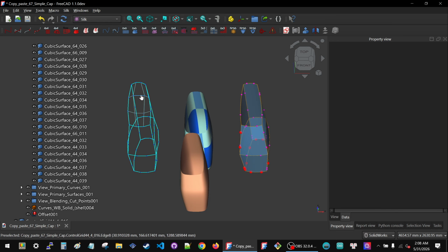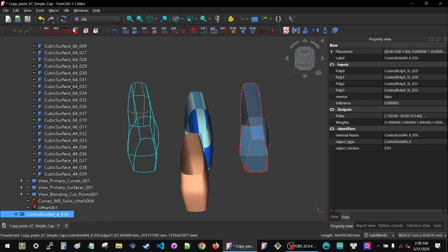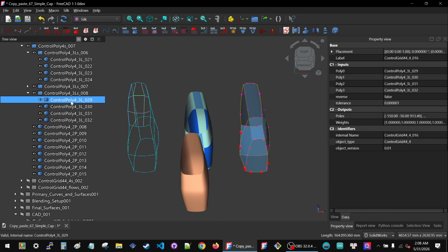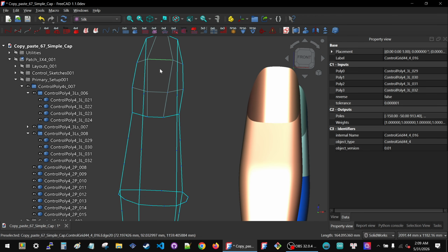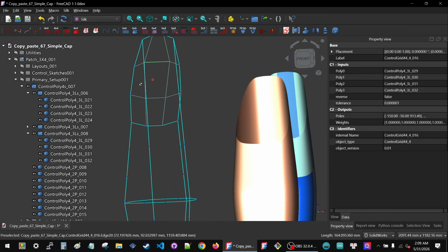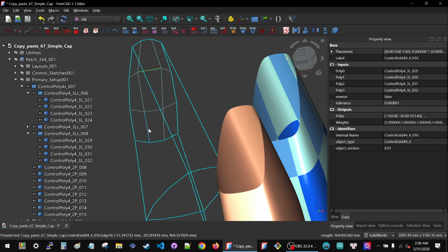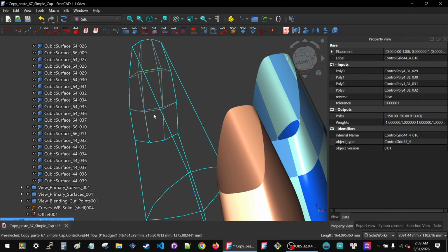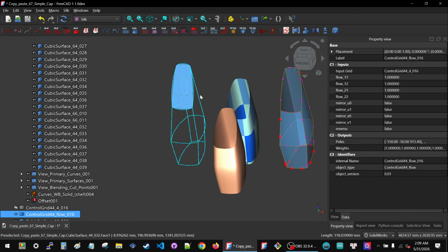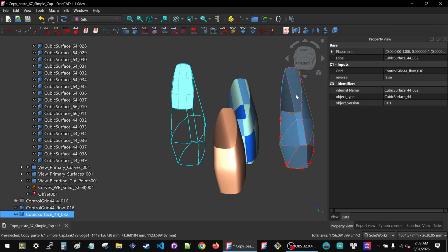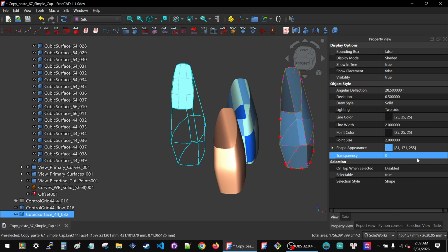Okay. I have this object, I have this grid here. I could give it a flow grid. You know what? I'll do that. I'll give it a flow grid because I did it on all the other faces. So right now this is the default grid, which has parallelograms in all the corners. I'm going to apply the flow grid, which smooths things out. Okay, I still have the first grid I created selected. I'm going to hit spacebar, and now I see the second grid, the flow grid. Okay, on this flow grid, I'm going to put in a surface. I'm going to make this surface 50% transparent, like the other ones.